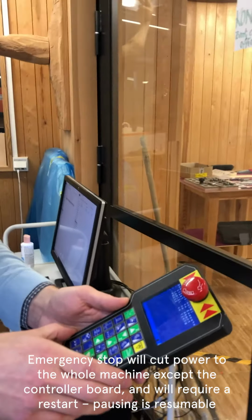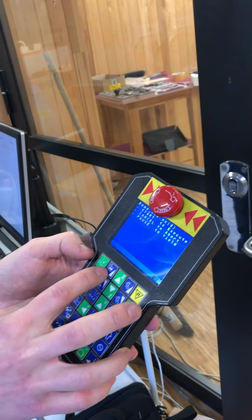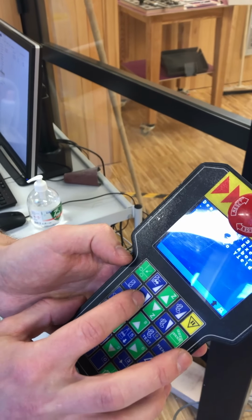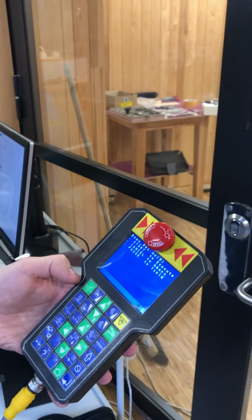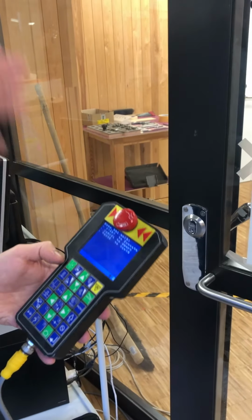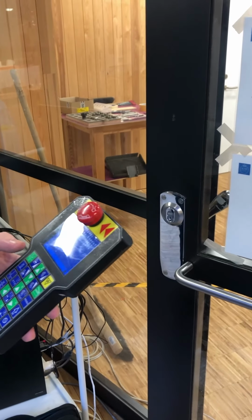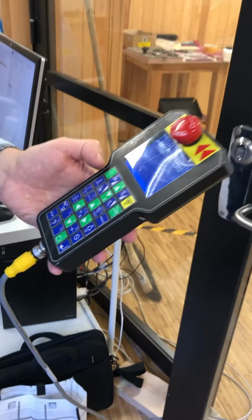All right, and before we even start as well, to the left of the Z jogging is the feed rate, adjust up and adjust down. And the feed rate will always start at 100%, and 100% is the feed rate that you set in Fusion 360. And now you remember that I intentionally increased the feed rate a little so as to be able to decrease it and test it out, so that you get the feel also for when it sounds good and when it sounds not so good. Okay, so you can't go over 100 in this.